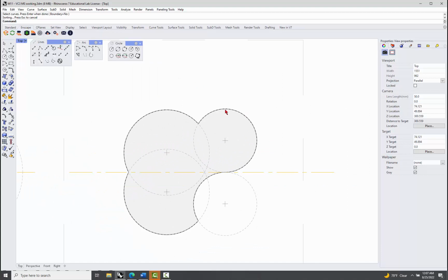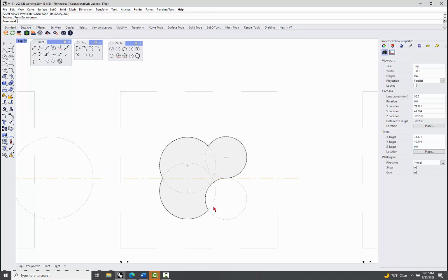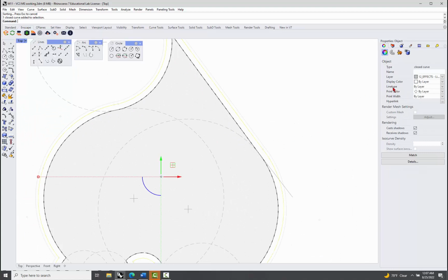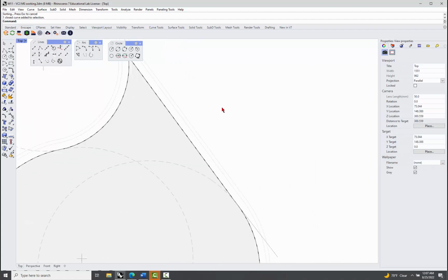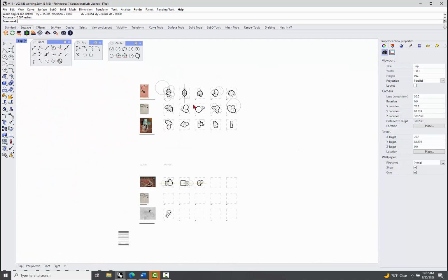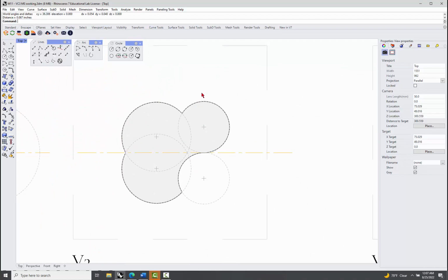There's also a sort of a little ghosting offset that's happening. So I believe, let's double check and see what layer that guy is on. Effects light, right? And then we can do the same distance, I guess. 0.125, and then 0.0625, an eighth and a 16th. So I'll just come in here and do offset, and it's set to 0.125, so that's fine.